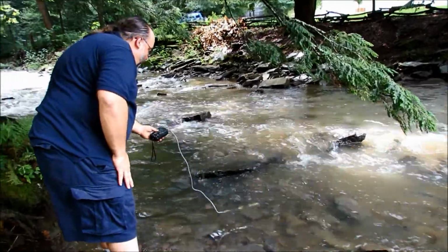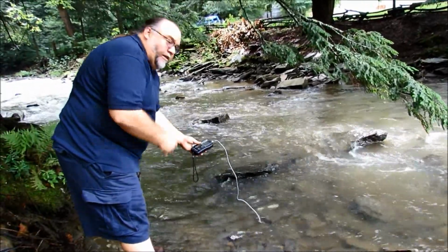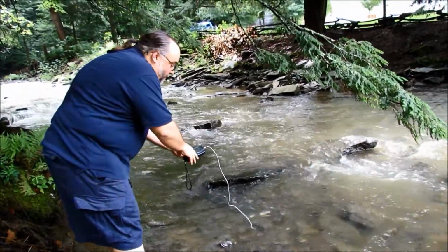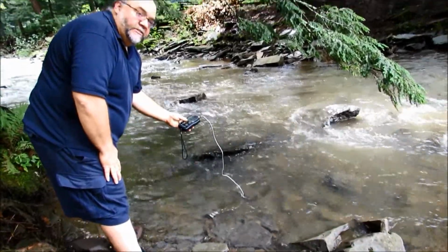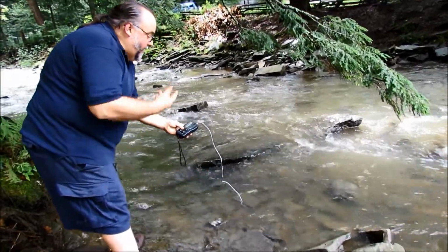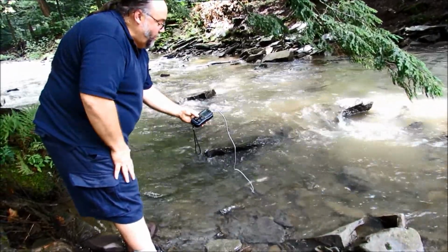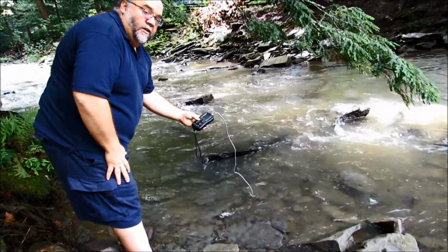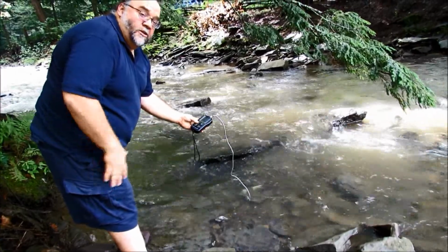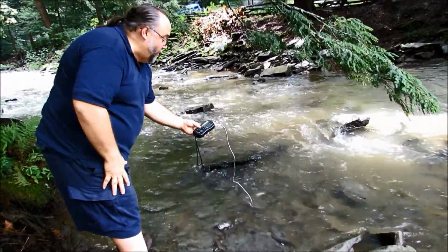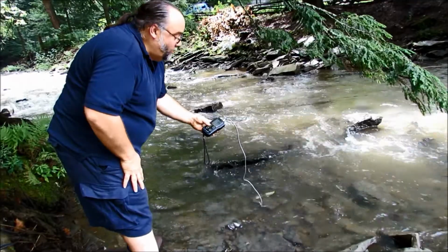That's where I'm at. And this one, it does pH. Okay. So right now the pH of the stream is 7.6. I can then read conductivity by just hitting a button. I already calibrated it. It has a conductivity of 70 microsiemens. That's very low. That's fresh water. And that's after a rainstorm.